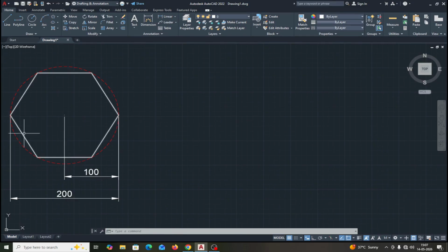A polygon is specified in three ways. One is the corner to corner dimension. Another is the flat to flat dimension, across flat faces. And the third is the edge dimension. So this method is the inscribed method.